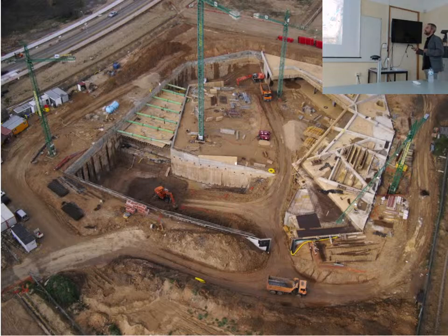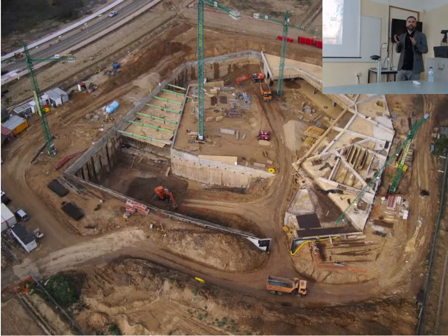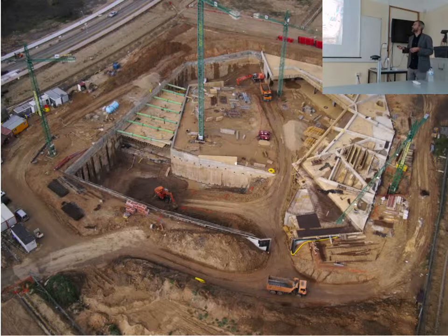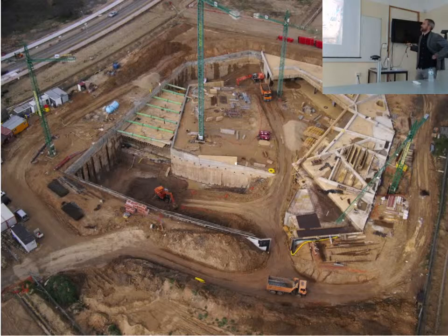This is the exhibition area, and since we have to have soil on top of it because it's all below ground, our idea was to have these inverted concrete beams just following the position of the columns. It seems like not a very orthogonal structure, and it's not, but it's simple because it's column to column, one inverted beam, and that's it. The arrangement of the columns came from the architecture, so it was not very orthogonal, but it was okay since it was going to be with soil on top.